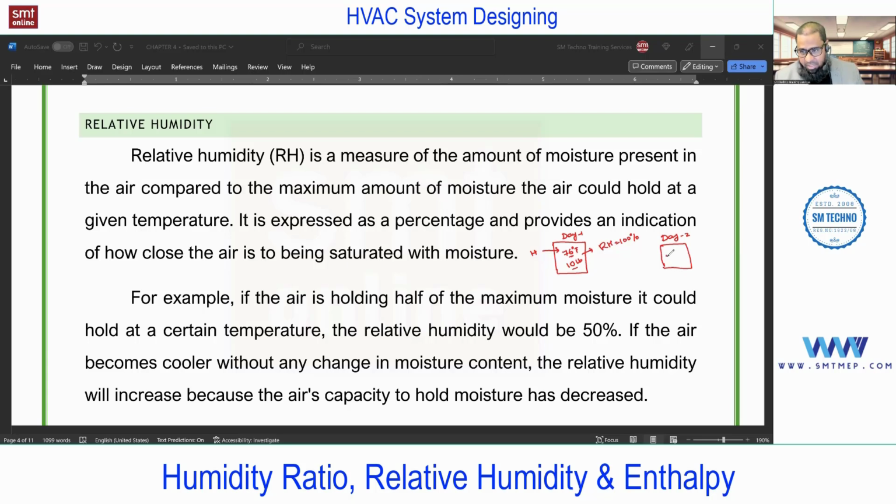Now on day 2, I'm maintaining the same temperature, 76 degrees Fahrenheit, and I'm not adding any moisture. I just measure, and I get say 5 pounds. So what can I consider the RH as? 50%. On what basis can I consider this RH as 50%? The base is the saturation condition. You cannot measure at a different temperature. At the same dry bulb temperature, when you compare the present moisture with the moisture when the air gets saturated, that comparison is nothing but relative humidity. That is, what the maximum possible is and what the present is.